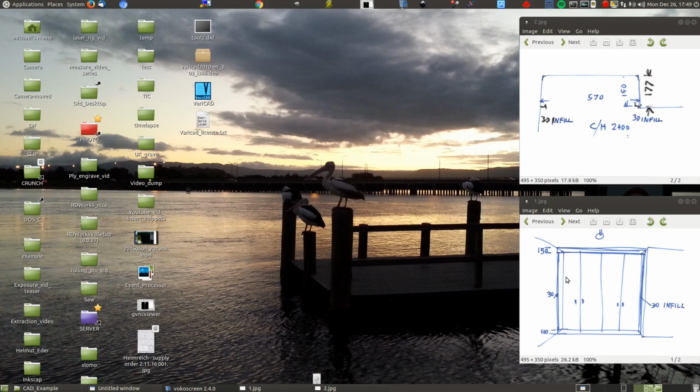Now I'll explain those two words. A plan view, think of the word plane. Plan is simply a variation of the same word. It's the basic meaning of horizontal. So this drawing shows you what you see looking down on a horizontal flat surface. That's what this view does. So you're looking down from above to the floor.